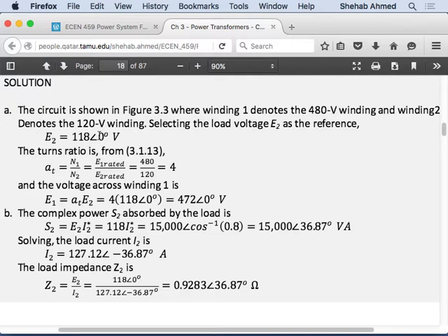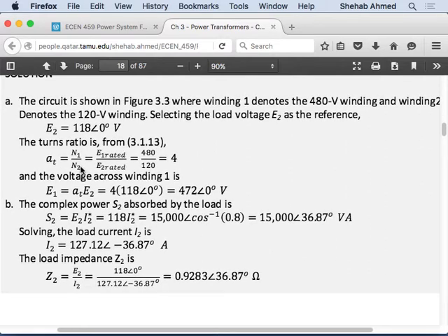From a phasor perspective it's the same, because the current will lag or lead based on the value of the impedance itself. You make the voltage point in this direction, it doesn't matter. With a certain impedance, the phase shift between the voltage and the current is fixed. If you move the voltage angle 20 degrees plus or minus, the phase angle between voltage and current will be the same.